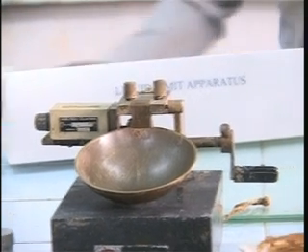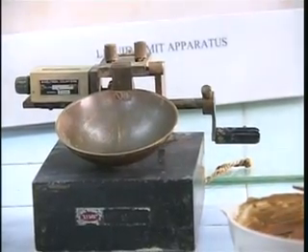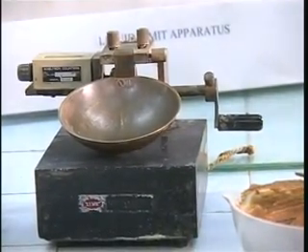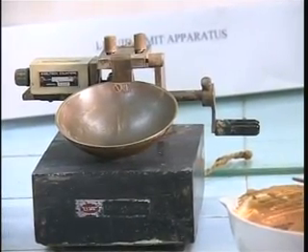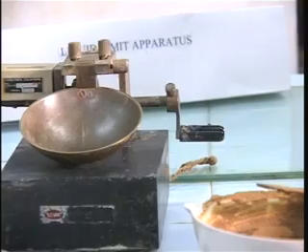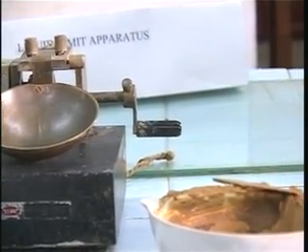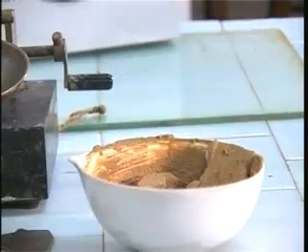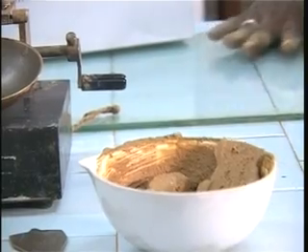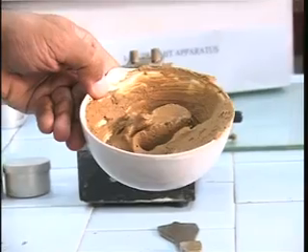Okay, so here we have the demonstration for the experiment which we use for finding out the liquid limit of fine grained soils. This test is typically applicable for soils with grain sizes finer than 425 micron. So if you have in situ soil which has some coarser particles, the soil is washed to remove particles coarser than 425 micron, and what we have here is a sample which is already screened through 425 micron.